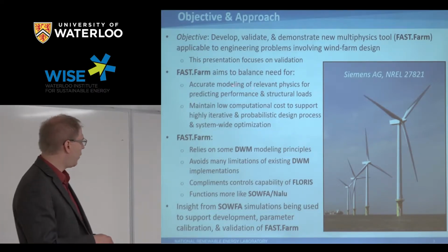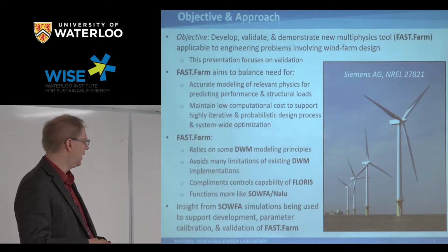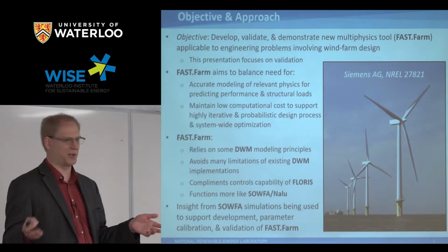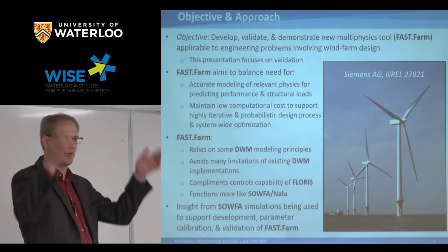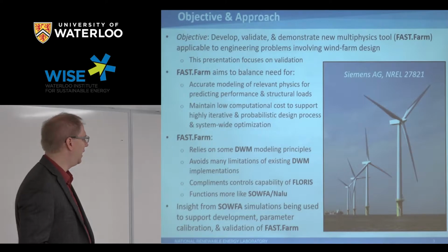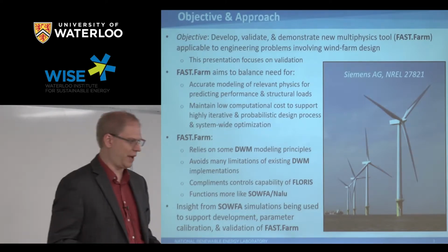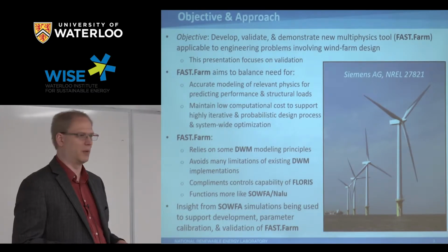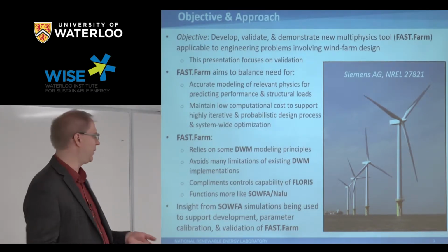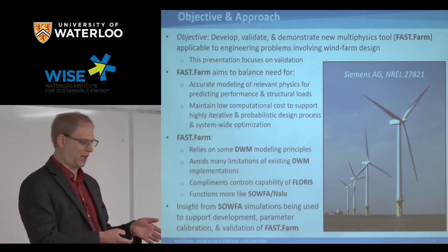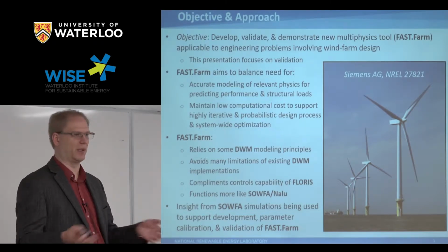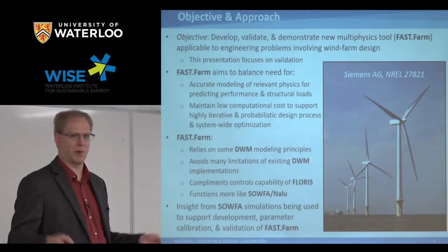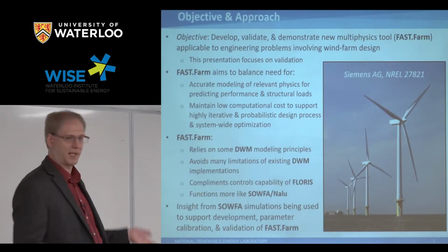But we also want to be able to run these calculations in a design loop. Normally, it sounds like you work for DNVGL, you understand the design process. You have a bunch of load case simulations. Usually, when you're doing a turbine design, you have on the order of 1,000 10-minute simulations you need to run. If you can set it up one day and get the answers the next morning, if you can run those 1,000 simulations overnight, then you can tweak the design and do the optimization. Within a few weeks, you have a really nice design. And that's standard industry practice.